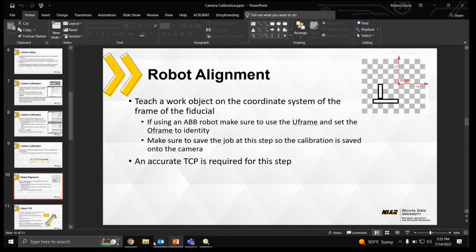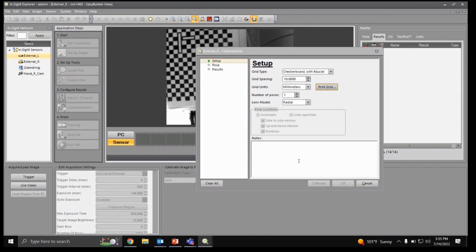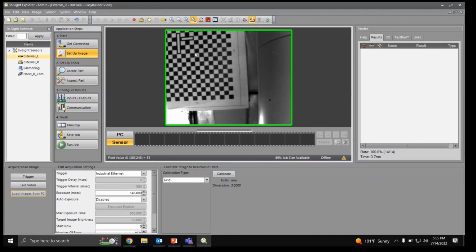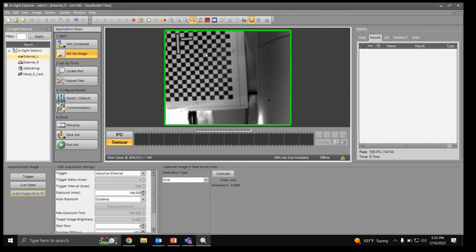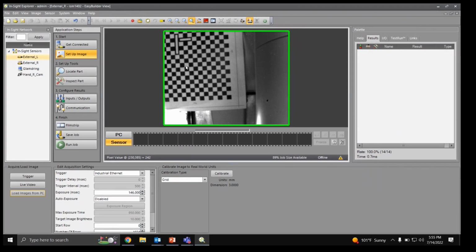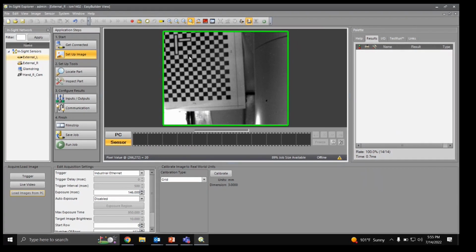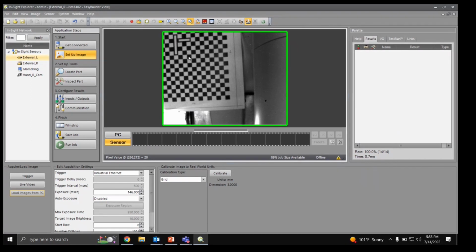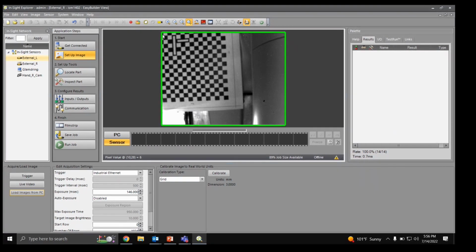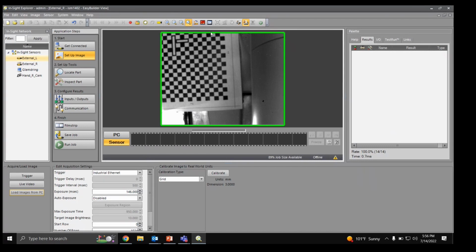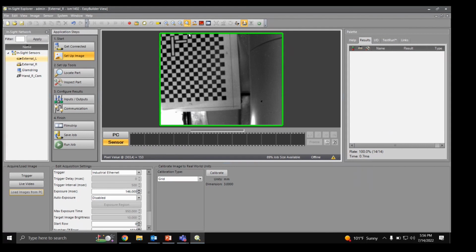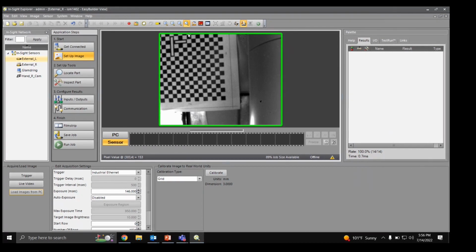That means if you put your fiducial, such as in this case, clear up in the top left-hand corner of the image, this means that my origin for this image is located up here, and it's actually slightly angled. So just for simplicity's sake, a lot of times we do try and put the fiducial in the center of the camera. Just makes life a little bit cleaner and more sense. Or you can actually try and put your fiducial clear over at the edge and just visually line it up with the camera frame. That's nice to do whenever you want to make sure all your values are positive, for example.